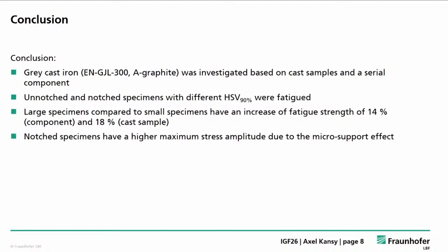And so I would like to ask you if you considered the size of the defect at the origin of the fatigue crack to try to understand which was the defect population that led to the fatigue failure in the different specimens that you analyzed.